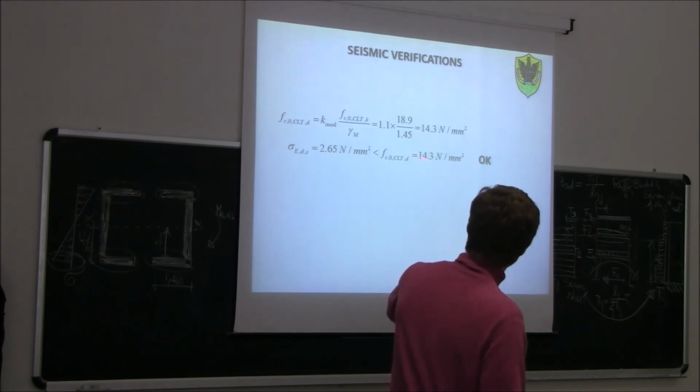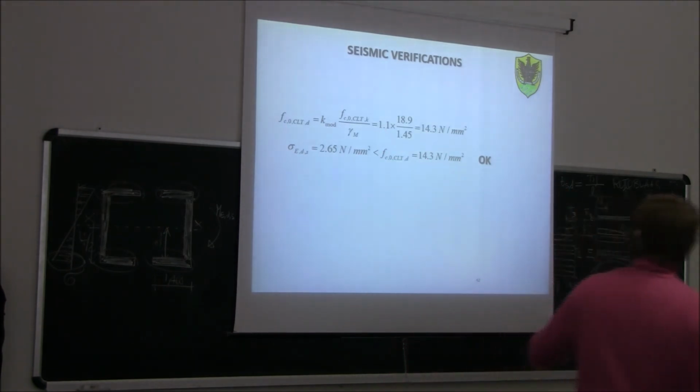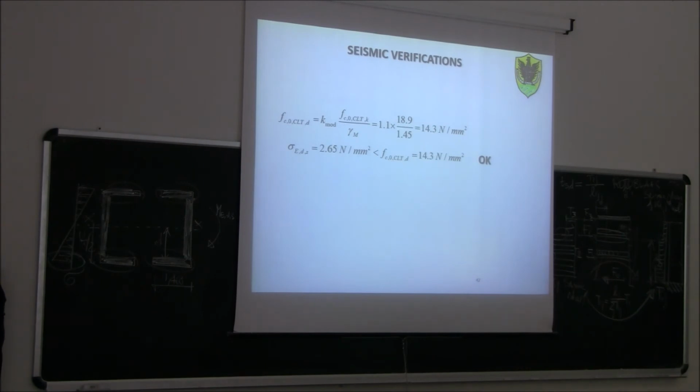Now we compare the design value with the strength demand. You can see that we are far away. So basically, the strength demand in the cross-lam panel is by far distant from the strength capacity. In fact, as I was telling before, usually we don't have problems in the cross-lam panel itself. We can have a problem only when they're used as a floor. If they're used as a floor for long spans, like 6, 7, 8 meter floors, then we may have some problem. Not a problem of strength, ultimately, but of excessive deflection. But when it comes to strength control, usually the cross-lam panel is not a problem.